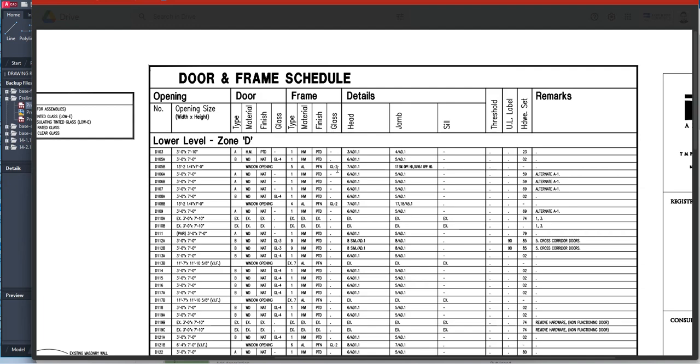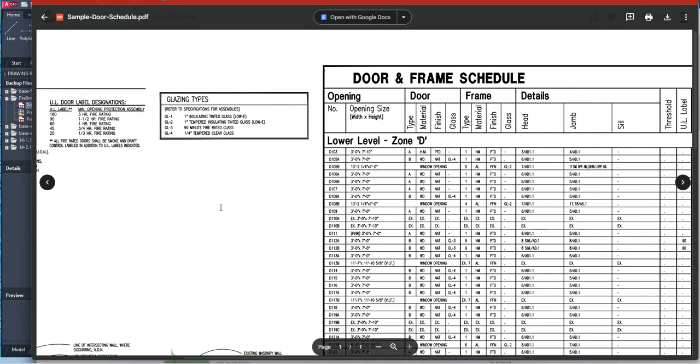And then if there's any glass again, you're going to put that there. GL4, GL2, so your glazing type. GL4 is 1/4 inch tempered, GL2 is 1 inch tempered. So that's very thick, whereas it's only 1/4 inch tempered here. This is a 1 inch tempered tinted glass, low E. So this is mostly for outside doors. This one's inside, so there's really no argon gas in between. So if you have an exterior door with glass on it, you may want to specify a 1 inch tempered glass.